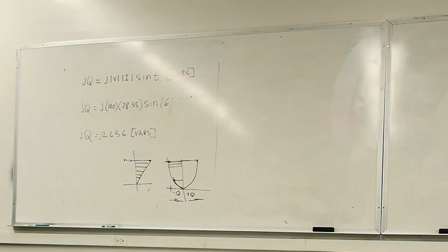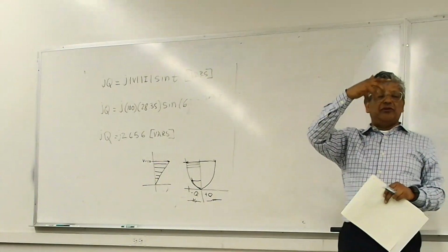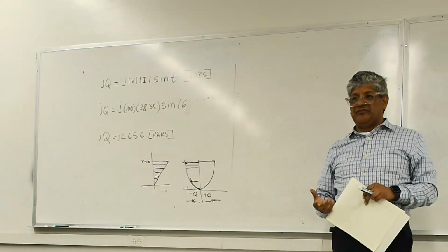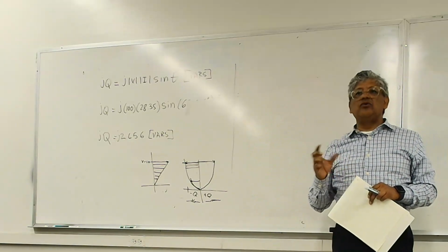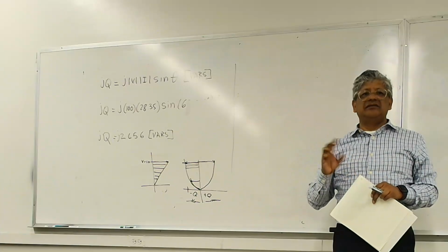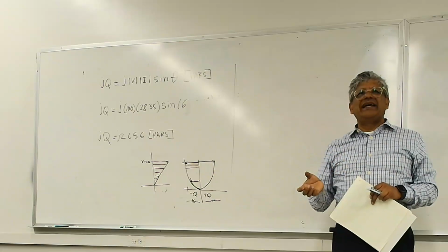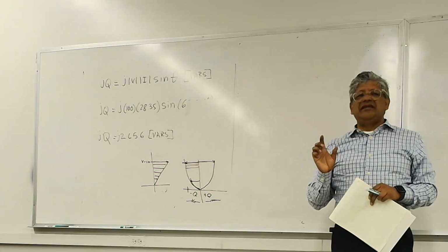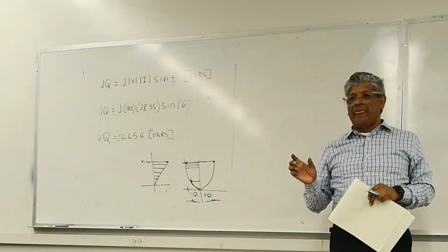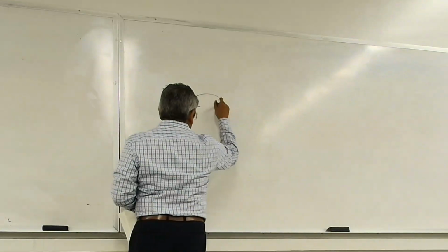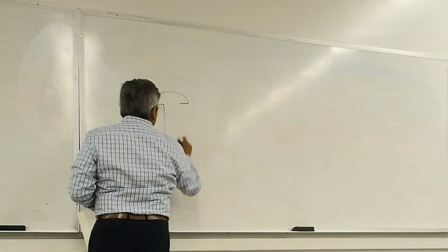How you do it is the synchronous machine has an external source. A synchronous machine has two sources. It has the three phases from the utility, A, B, C, but in addition to that, it has a DC source. How you adjust your DC source is how you change the behavior of the synchronous machine. As I said, we're going to talk in more detail, but I'm going to give you some preview.